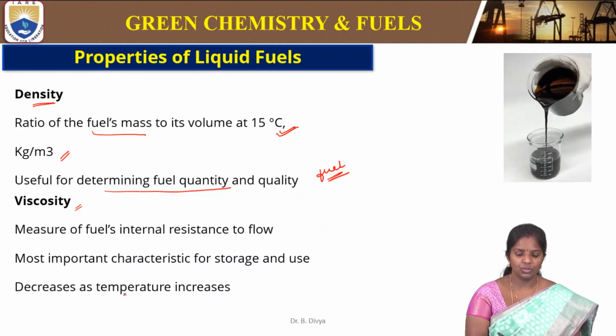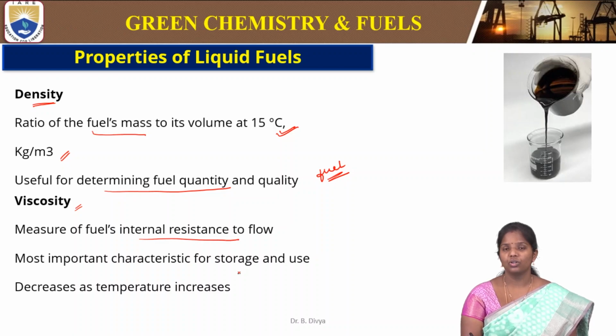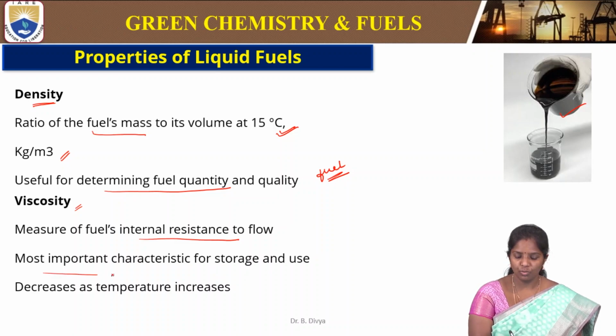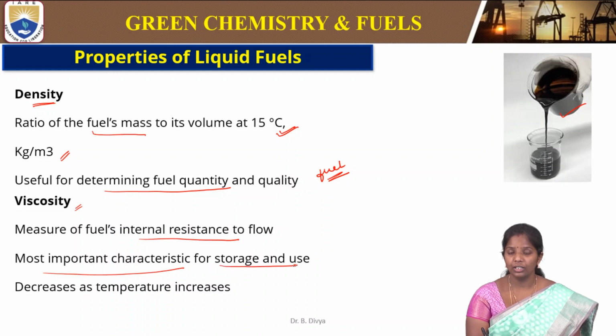The next one is viscosity, a measure of the fuel's internal resistance to flow. Viscosity is nothing but the thickness of the fuel. It indicates how the fluid is restricted to flow. This is the most important characteristic for storage and use. Even for storage we have to consider viscosity, because depending on the viscous nature, the storage capability can vary.